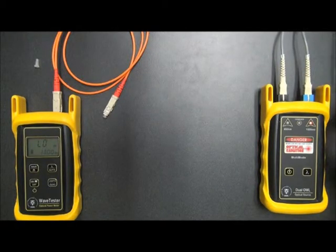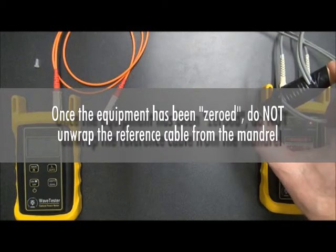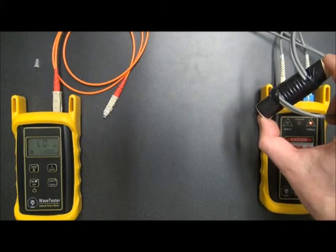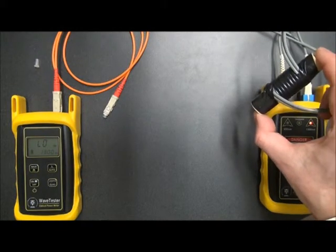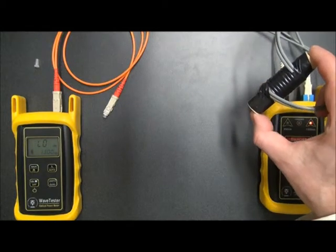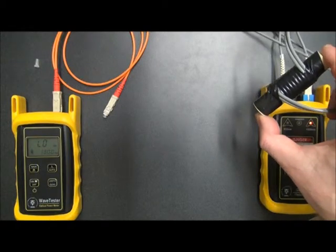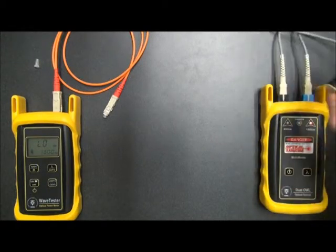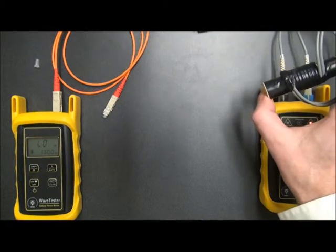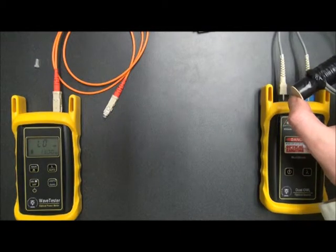The other thing you want to remember is to not let the patch cable unwrap from the mandrel. For the same reason, you want to make sure that the reference stays intact. If for some reason the cable unwraps from the mandrel, then you will have to re-zero and possibly do all your measurements over again. So just remember, do not disconnect from these ports and do not unwrap from this mandrel, at least until you're done testing and you're satisfied with the results.